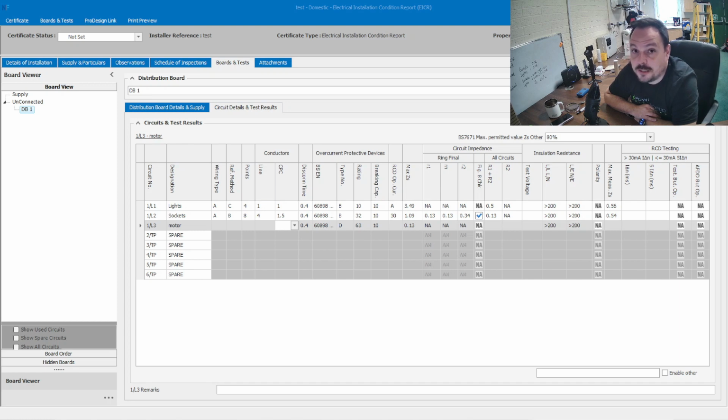And I think if we teach people that, they'll have an understanding of how to do it safely, so when they're stood in that situation where they do need to record a value of their fault loop impedance, and there'll be occasions you have to do that anyway because of manufacturer instructions or a specific work environment you end up being in, be it rail, military, healthcare, they're going to know how to do it, and they're going to know how to do it safely.